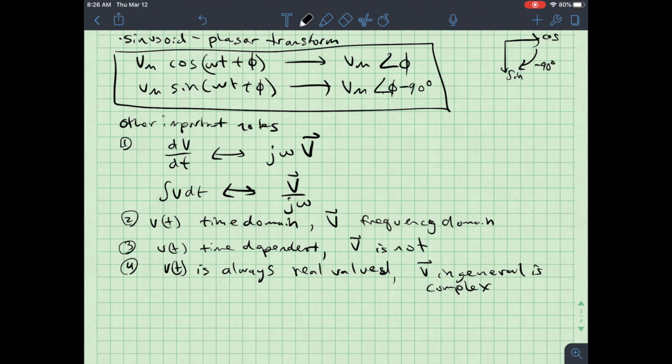And then the last note here, which again I said verbally: phasors only work if all of the signals in the system are of the same frequency. So they only work for signals of the same frequency. And that becomes really important when we talk about superposition in alternating current AC circuits in a future lecture.